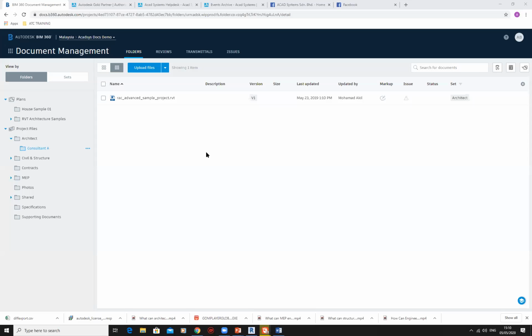Okay, after a new model or plan is uploaded, is the old markup tied to the old model or the new model? Similar to an issue created, what happened to the new version model? Sometimes we upload the wrong drawing. Can we delete it, and after it is deleted, what happens to the version numbering? Okay, renumbering is automatic for any new models that are uploaded. The old markup will stick to the old drawings.